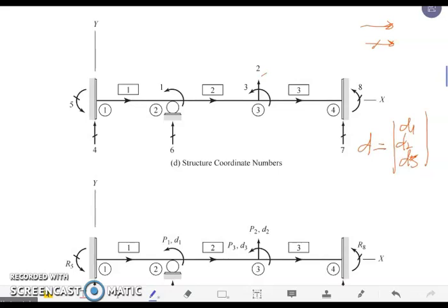We have restraint coordinates for translation along the y direction, and of course restraint coordinates for rotation, so it will have an arrow with a slash. Since we ended at 3, we continue our numbering. We number first the restraint coordinate on translation along the y direction, so that is 4, followed by rotation as 5.